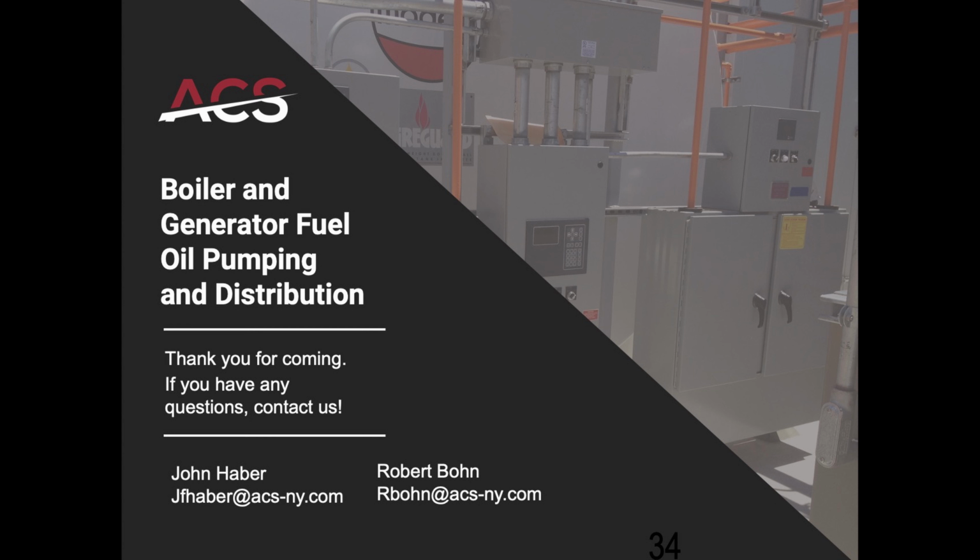Excellent. A few more here. Why is there a requirement in New York City for fuel pipe risers to be enclosed in a masonry enclosure, and for the pipe to be 4 inches from the interior of the wall of that masonry enclosure? Single wall pipes running up risers, the oil carrier pipes in the buildings. The 4-inch masonry is for your fire rating. And the spacing is a conservative design for pipe flex.